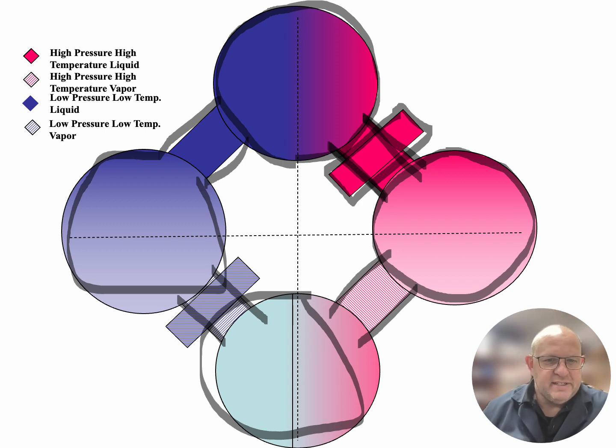So when we look at the different states of the refrigerant, I always like to refer it back to water, and as water's absorbing heat and rejecting heat, what happens to that water. And when we look at this refrigeration diagram, what we're actually looking at is what these four components are doing to the state of the refrigerant as it's moving through the system itself. Every component named in the refrigeration cycle is named for the things that it does to the refrigerant, either absorbing heat, such as our evaporator, or rejecting heat, like it does in our condenser.